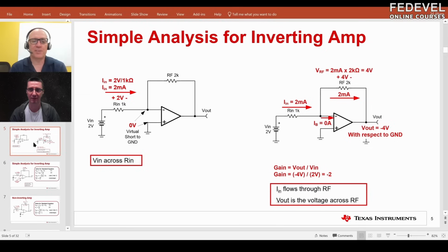Sure. Basically, any analog signal, such as audio or pressure, or later we're going to see a pH demo, any kind of thing that you're measuring, usually that signal cannot be directly connected to an analog to digital converter. Ultimately, you want to take analog signals like light and sound and convert them to a digital signal so that you could process it. But you have to have some way of boosting up that signal or amplifying it so that the analog to digital converter can accept it.